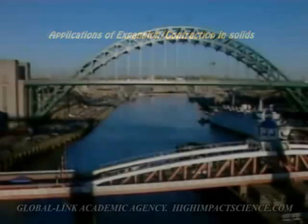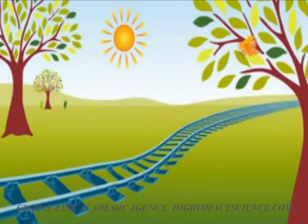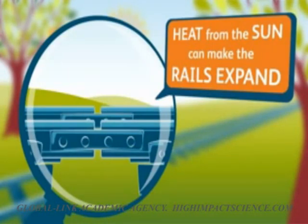Applications of expansion and contraction in solids. Expansion of solids can cause problems. Railway lines, for example, may buckle during hot weather. So expansion gaps and sliding joints are built into the trackwork. Railway lines are constructed in sections held together by fish plates. The bolt holes are oval shaped to allow free expansion and contraction of the rails with changes in temperature.